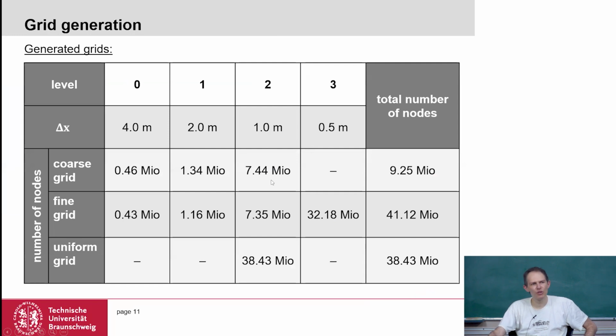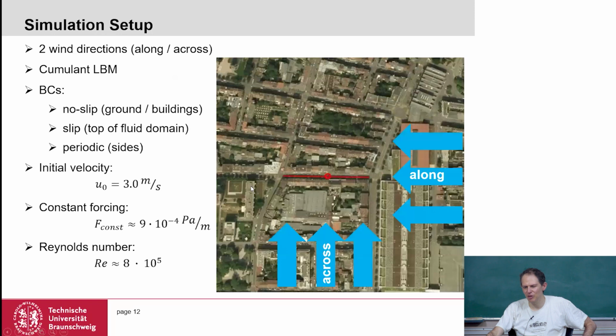If we have a resolution of 1 meter and non-refined grid, then we could do this even 6 years ago. We could do this on a GPU for a domain of 550 by 550 by I think 130 meters. We could do this on a desktop computer with 1 GPU in double the real time if we are just dealing with the flow, at a resolution of 1 meter.